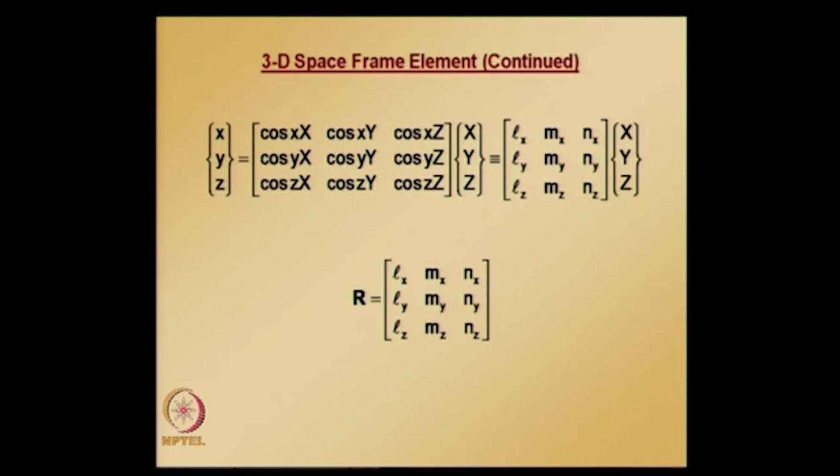There are 2 methods to accomplish this. The first method needs an orientation angle, and the second method needs coordinates of a third point that explicitly defines either the local xz or local xy plane of bending. Formulas for calculating these direction cosines are based on the 2 methods I just mentioned: one is called the orientation angle method and the other is called the third node method.